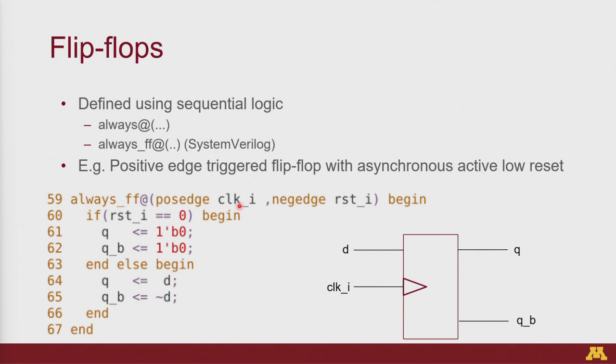So the difference between a synchronous flip-flop and an asynchronous flip-flop is that a synchronous flip-flop means all your operations happen on the clock edge, including a synchronous reset. This would mean that in terms of code, this block would just not be here. But if it's an asynchronous reset flip-flop, it means that as soon as a reset comes, the entire design gets reset.